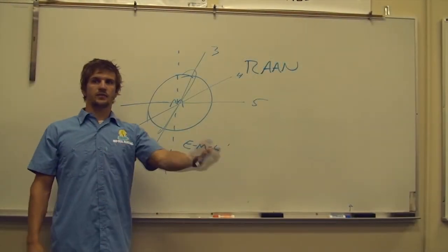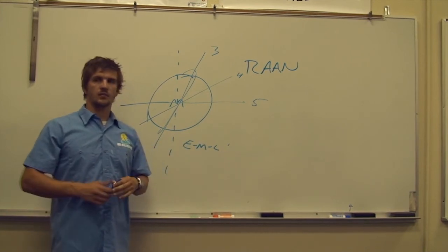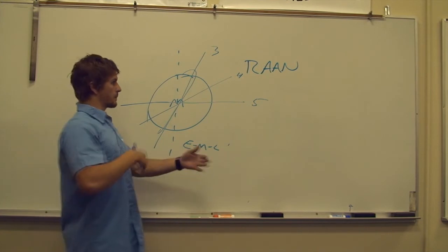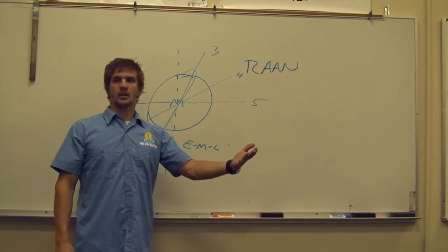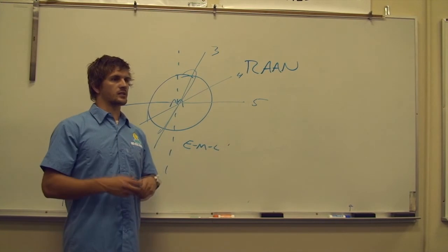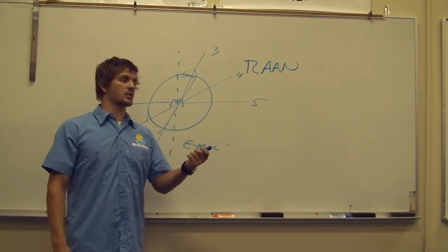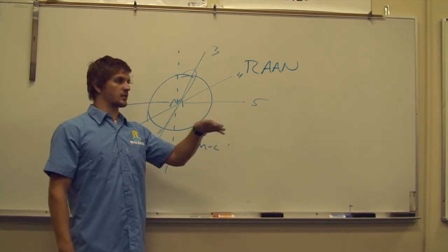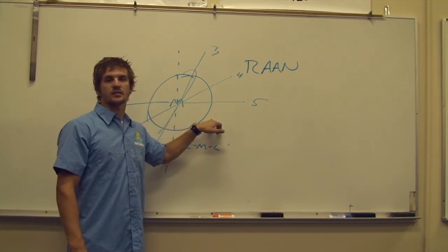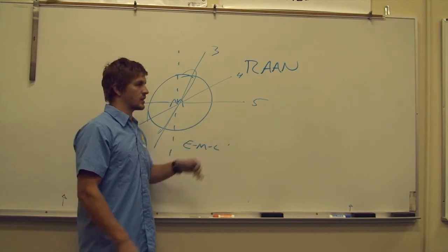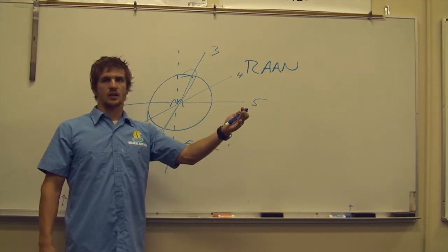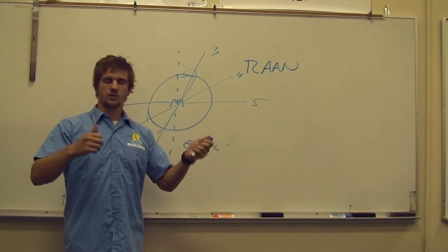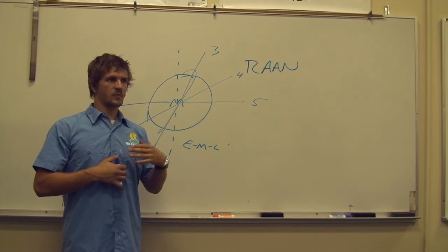Alright, the last phase, which is the most exciting, is our powered descent trajectories. Again, the method that we always put first is our direct method. This is essentially just going to perform a braking maneuver. You're going to slow your craft down to about 500 feet per second at an altitude of about 7,000 feet above the lunar surface. And you're going to brake yourself down from there using various descent methods, and this is where the two cross over and run about the same methods.